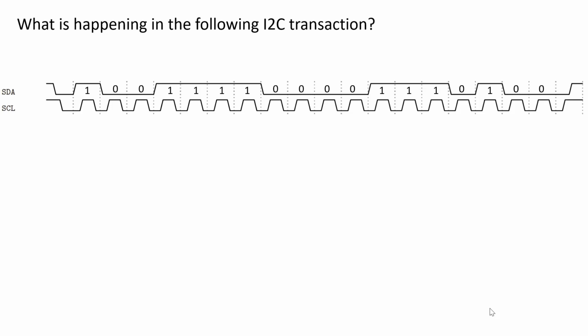So 4F is the address that we're writing, and the data we're writing is, that's the acknowledgement, so we start here. So 0011 is a 3, 1011 is an A, so 3A. Make sense? So we're writing 3A to address 4F.